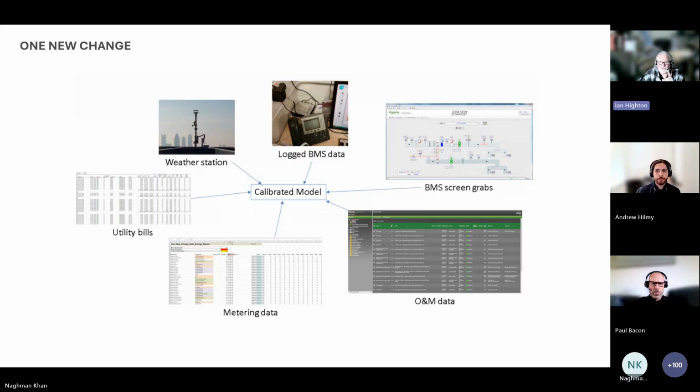So I was actually up on the roof, and I think I took that picture. That's crucial, because that gives you the right solar data, the right temperatures, the right wind speed, the right wind direction to base your building simulation on, which you can then push through to the system simulation.